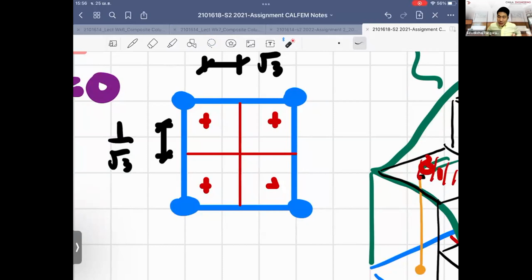So basically, there is a relationship with the order of the shape function. If you use a bilinear shape function, you are allowed to use only 2x2 Gauss points. If you use a quadratic shape function, you can use perhaps up to more Gauss points.